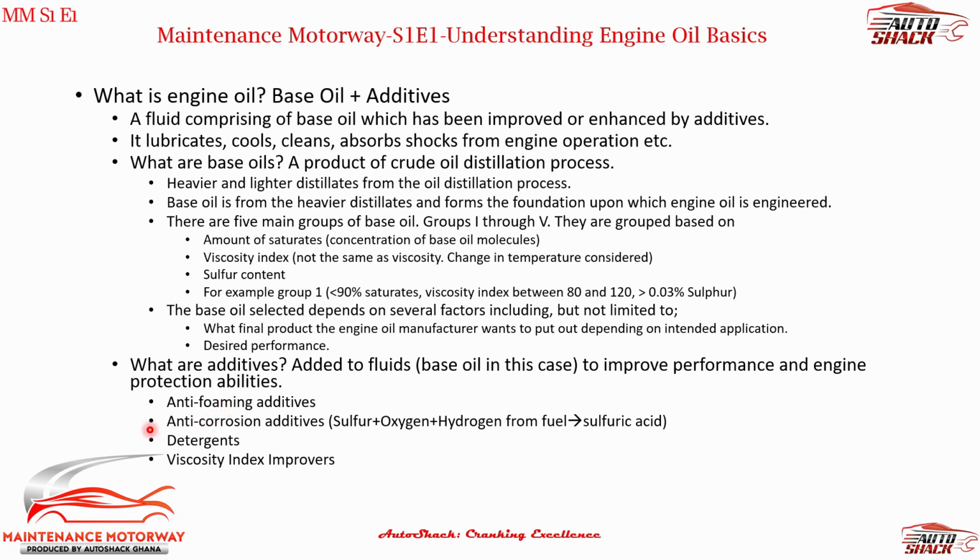Now anti-corrosion properties, I already talked about that. You have sulfur combined with oxygen and hydrogen to form sulfuric acid, which is super corrosive. And you have detergents, which the name is basically self-explanatory. It just cleans the engine. And then viscosity index improvers. You're going to be operating the vehicle under different temperatures, and you want the engine to be able to hold up. So you need the oil to be able to protect the engine under all the different conditions.